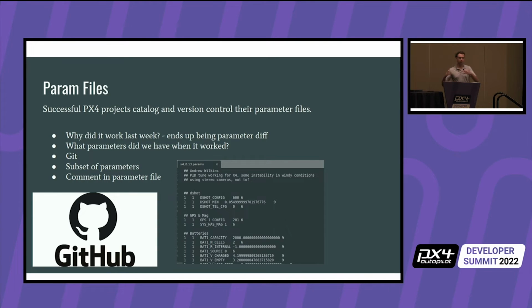And they load up the parameter file from an email that was sent off 2 weeks ago between 2 employees, and all of a sudden they go, why is this parameter different? And who changed this and who changed that? Because developers go in and they go, well, what happens if we change this? And then they'll go, well, we'll revert it back if it doesn't work. And then they crash the drone and they forget that they need to change it back, but they'll use the same FCU. And then it just gets this snowball effect of why aren't things working?